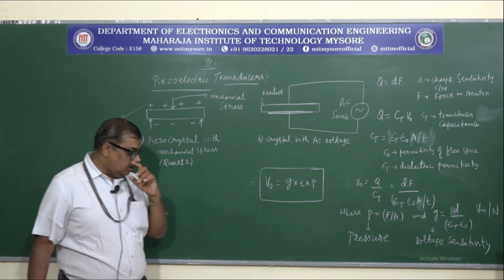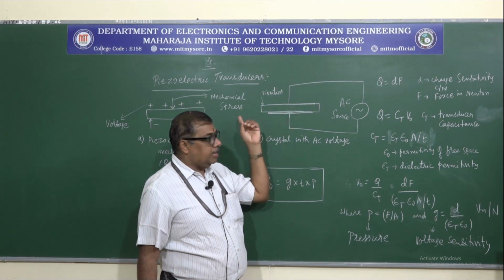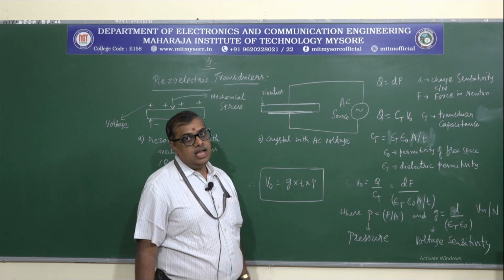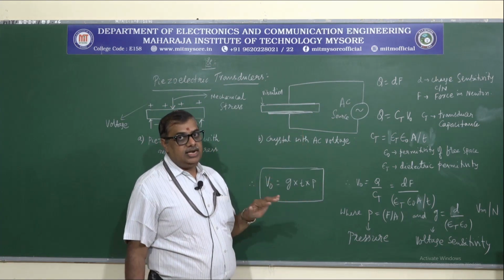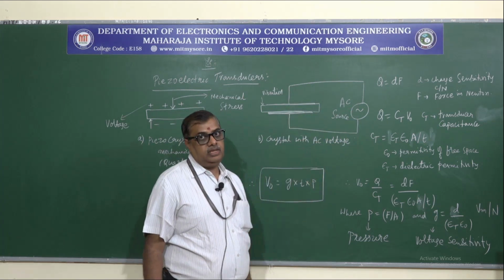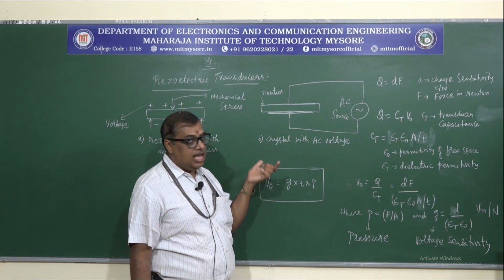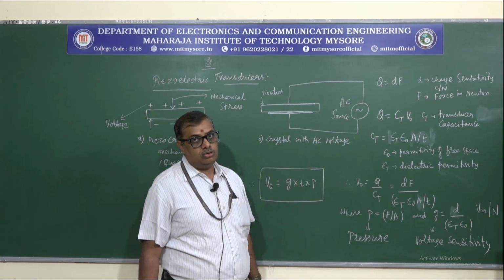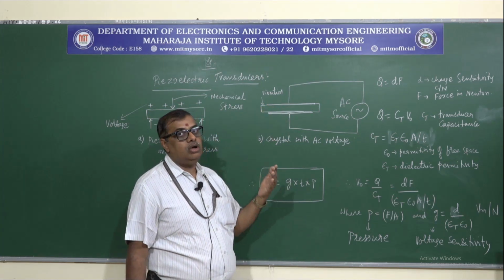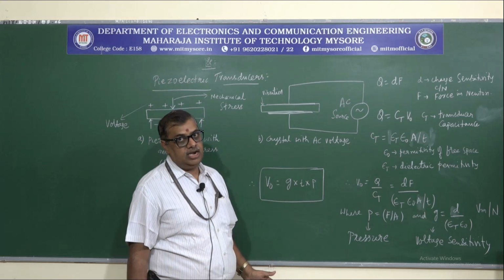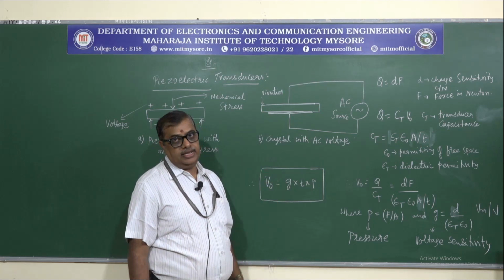Okay. On the other hand, if this piezoelectric bar, which you are seeing as a piezoelectric crystal arranged in the form of a bar, of say length L, is excited by an AC source, it starts vibrating. That vibration also produces mechanical stress, and that stress is converted to equivalent voltage.